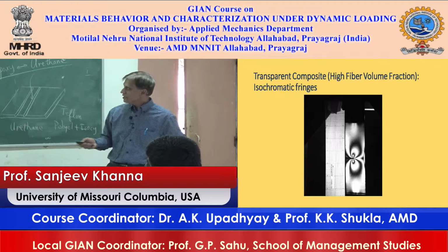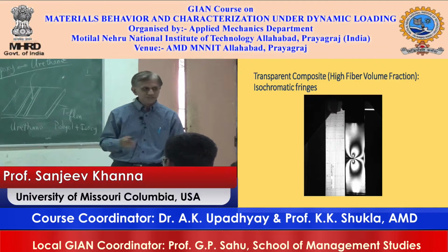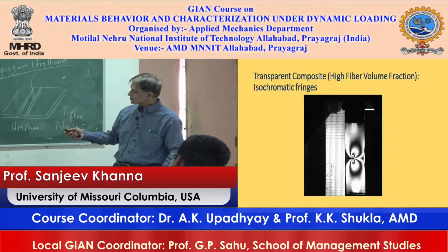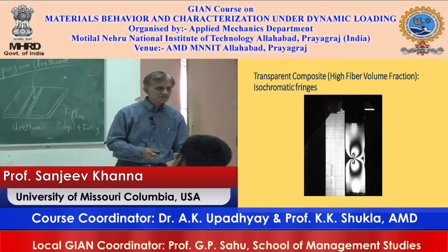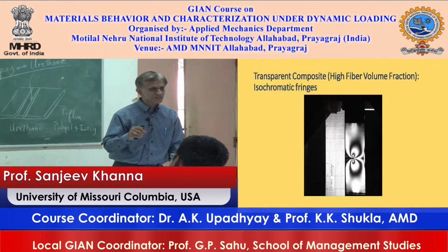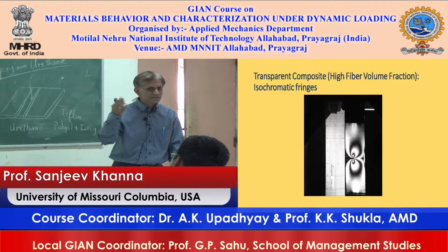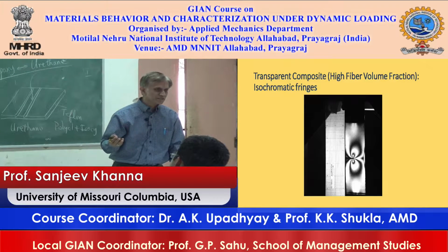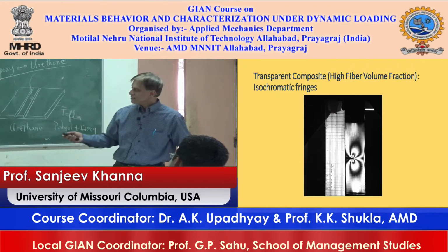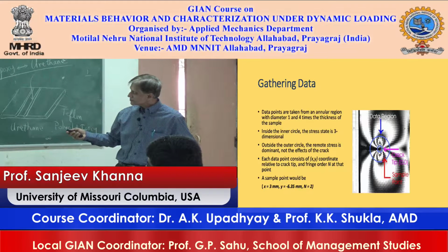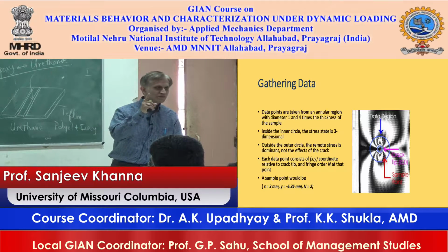I showed you last time that very close to the crack tip, a little circle here, we don't want to take data from there because that is too close to the crack tip. The stress state is not planar, it is three-dimensional. The diameter of this area that we don't take from is equal to the thickness of the sample.